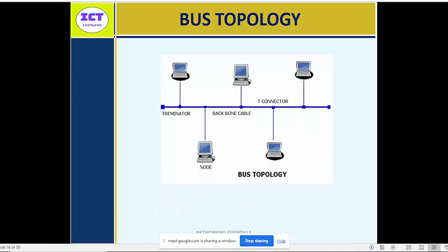One is that if multiple devices want to communicate, there's always a problem of ringing back of the signal. If one side is not terminated, they'll wonder who is communicating, because the line will be ever busy. So there won't be a chance for any communication from the different devices to happen. That's the main disadvantage.